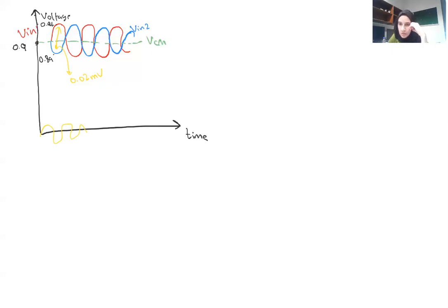Okay. Now, a question from Tanzil. In the half circuit model, we find the gain for half of the circuit, so will the total gain be double or remain the same? No, not double. It will be the same as the gain of the half of the circuit, with no doubling for it. Because we are working on the differential signal, the gain is equal to the gain of the half of the circuit and not double of it.